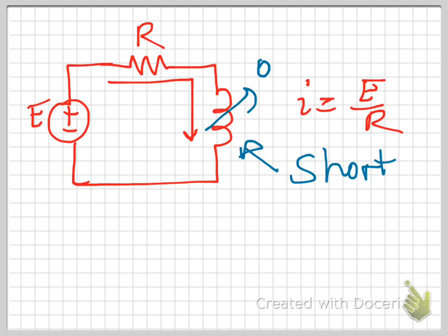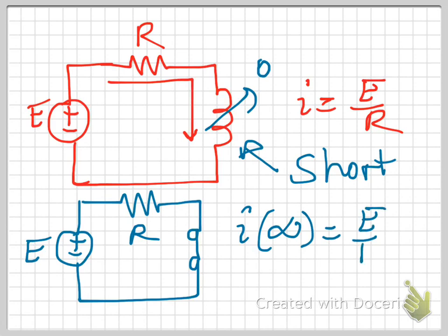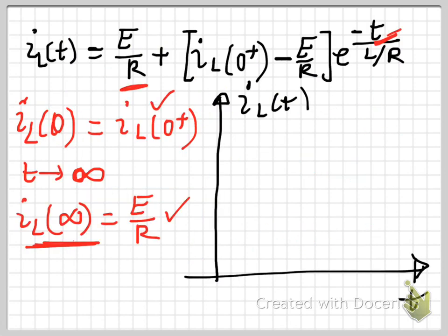So that means the inductor here at t equals to infinity is fully charged and can be replaced by a short circuit. So at time t equals to infinity, the circuit will simplify into this. So I at t equals to infinity is given by the value E over R. So going back to the graph, the first situation at t equals to 0 is here, at minimum current, and you can assume it as 0. At any time t tends to infinity, you can consider any time t in here, and its value is E over R.